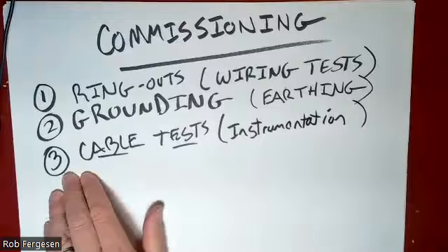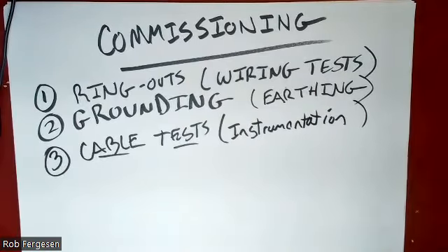So you want to make sure that all of your instruments can communicate over the wires that they're supposed to be communicating with. This is the layer of Ethernet. You have some Ethernet tests that will be part of this cable testing if it's an Ethernet-based system. You have Modbus. You've got RS-232, RS-485. You want to make sure that all of your communication cables and instrumentation connections are in place.